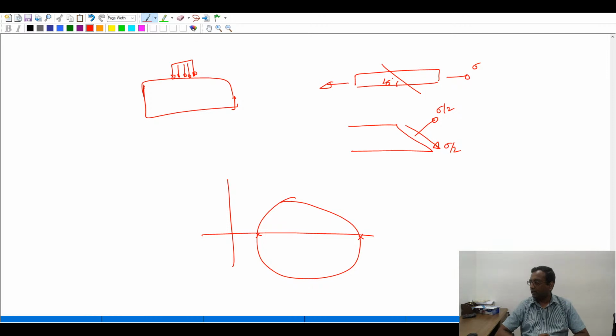Okay, why are you studying statics in SOM and not dynamics? See, the reason is many times the inertial forces are insignificant compared to the applied forces that are coming on the structure. And they don't vary with time significantly, and hence we study mostly statics in strength of materials or mechanics of materials and not dynamical effects. But it's not that no dynamics is considered at all. There's a separate course on structural dynamics which deals with the dynamical problems.